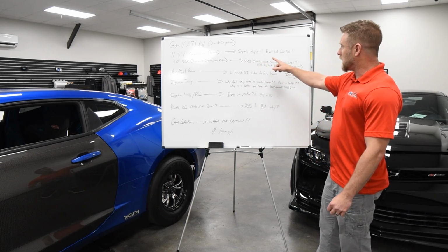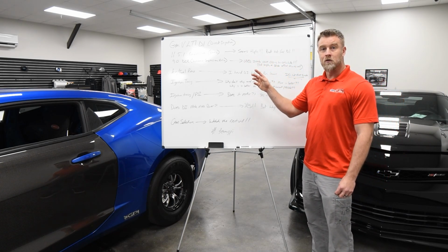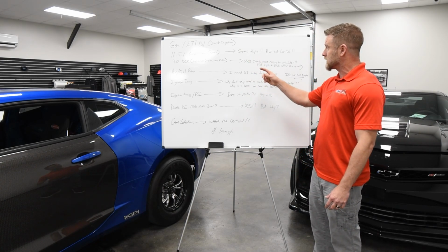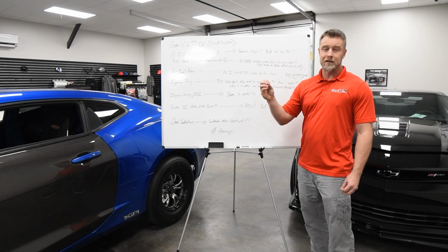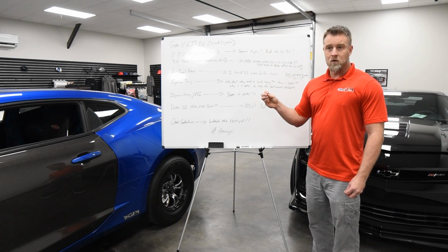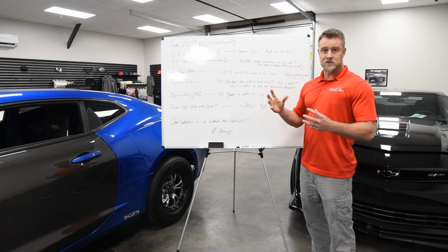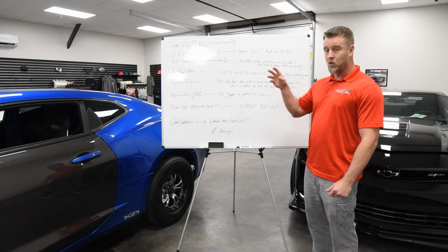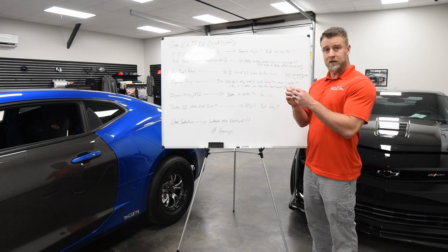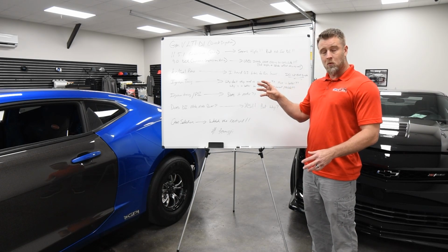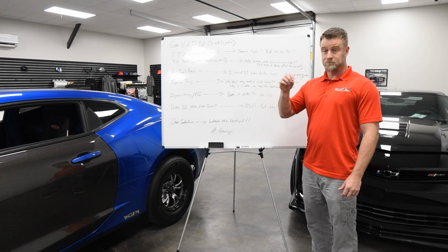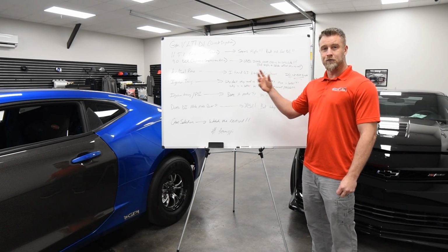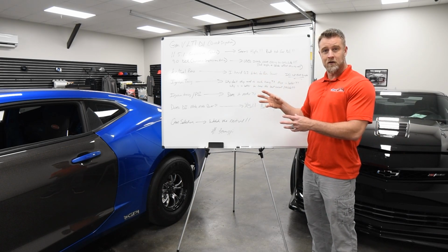So why is this not too much compression ratio for a direct injected engine? It's simply because the direct injection puts the fuel directly in the combustion chamber. So it gets a cooler, more atomized charge out of the injector versus a port-injected engine that puts it in the port, that will get fuel on some of the port walls. If you have oily ports, you can get oil contamination in the fuel from port injection stuff.